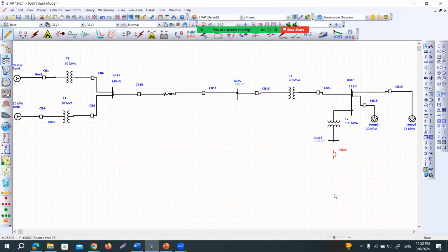You can click OK. Now you bring one more bus, sorry, here. Okay, so once you connect this one and you connect this one, the next bus will become 0.45 kV also, because they are the same voltage level. So finally, to complete the circuit, you bring another load, static load. So put it here.